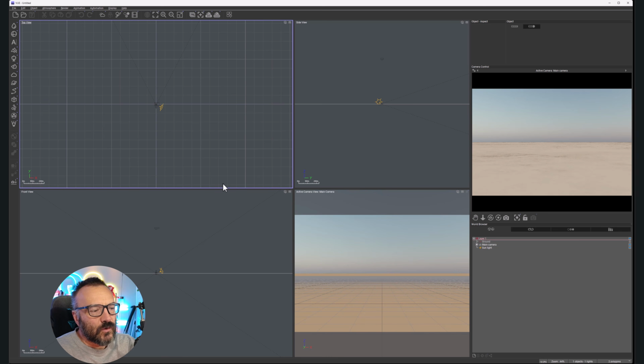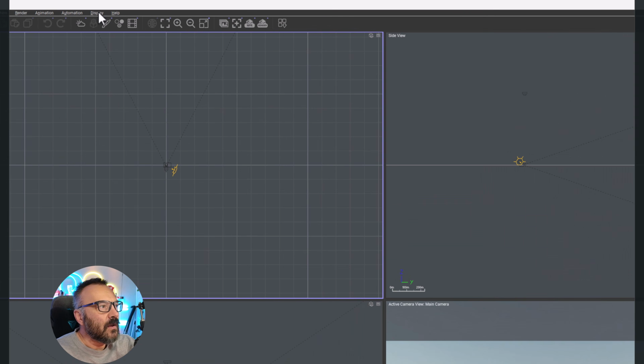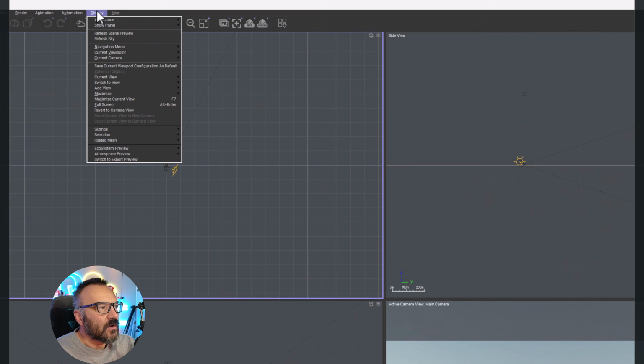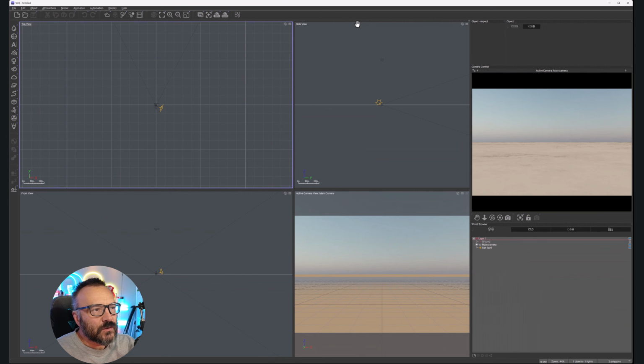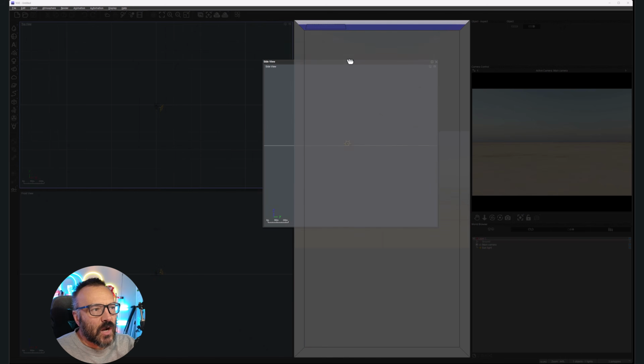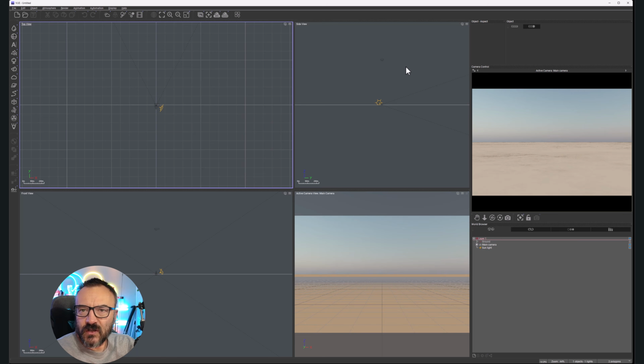In the middle, you'll notice we have 4 different views, and this is by default. All of these views, of course, you can easily modify by going to display, workspaces, and right here just uncheck lock workspace. Then you'll notice you have options. You can drag any of these and reposition or move them, even onto different screens.